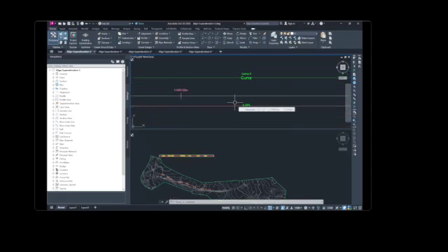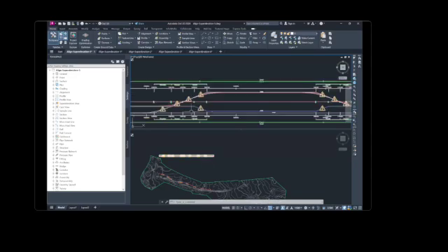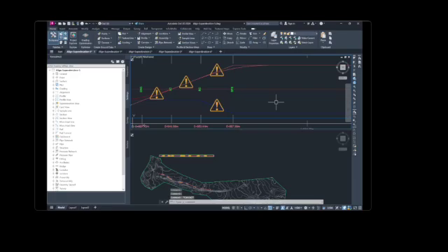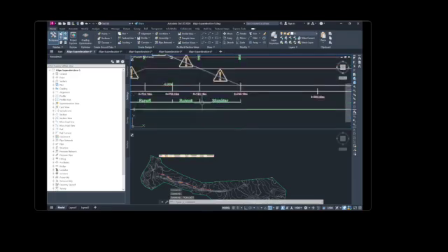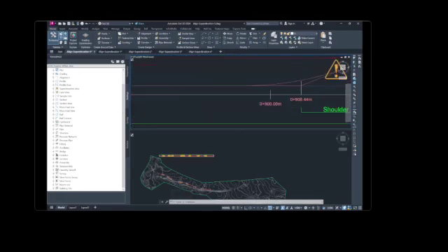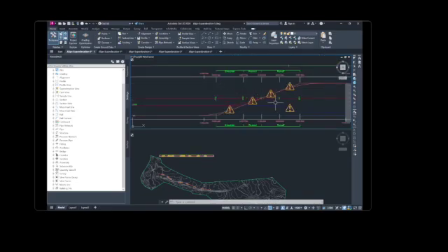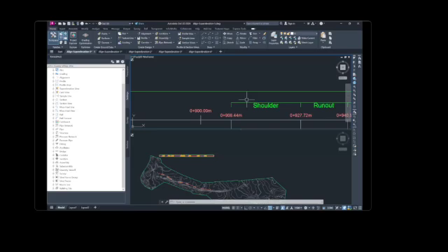In the curve 4 portion of the super elevation view, click any of the red or blue lines. We're going to press escape. Then move to a critical station graphically, near station 0 plus 900. We are going to control click the green shoulder text.